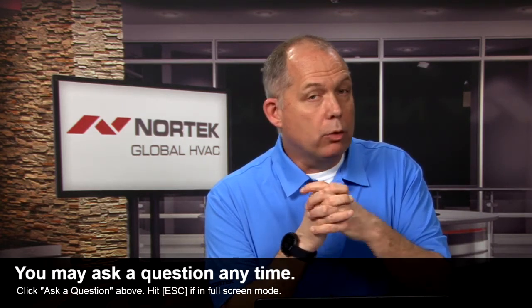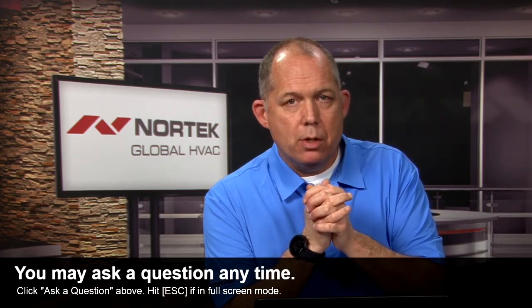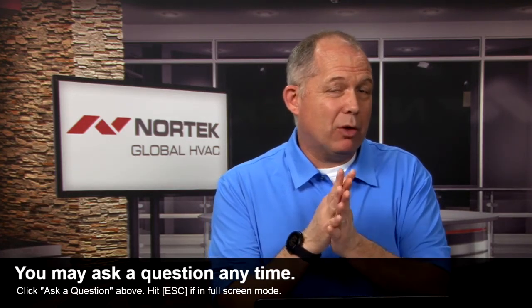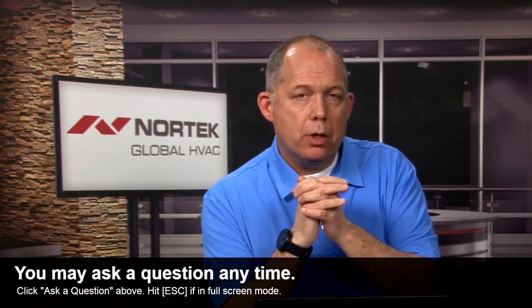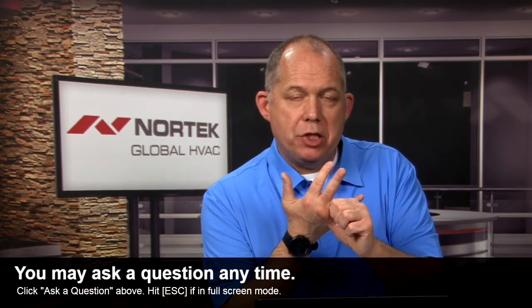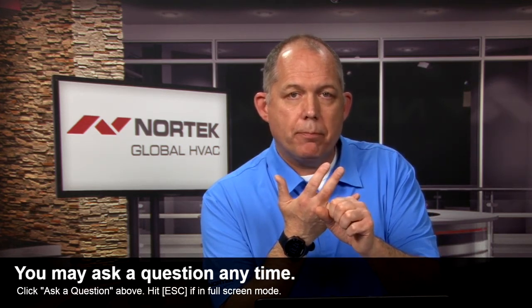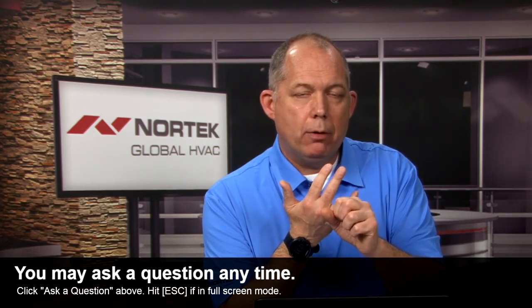Again, we're getting back to rules of thumb, the old rule of thumb of 400 CFM per ton of cooling no longer applies with these high efficiency systems. You're going to run anywhere from 325 to 350 in some cases, depending on the size of the equipment. In the Quick Reference Data Guide grids, you'll see a piston or TXV change if needed. It'll give you any additional refrigerant you need to add to that system. Remember, we send the unit with a factory charge, and then based on the indoor coil or air handler you're using, that charge may differ.